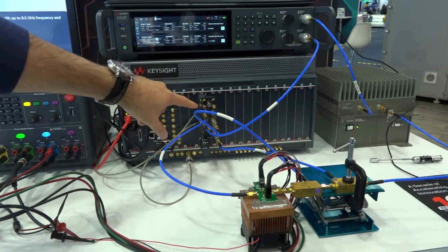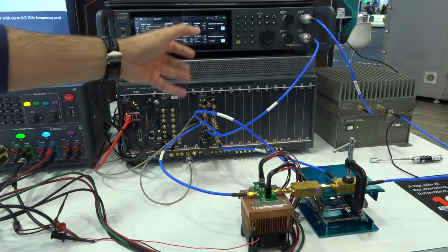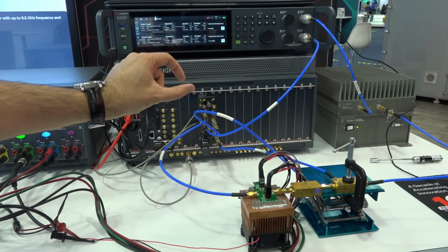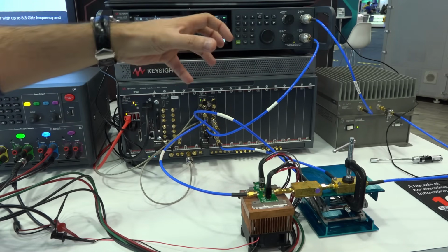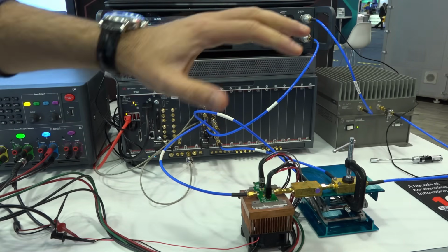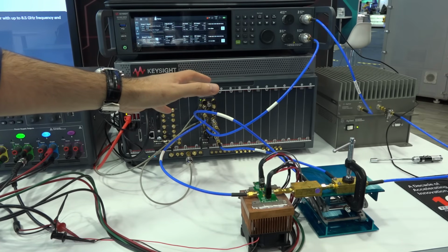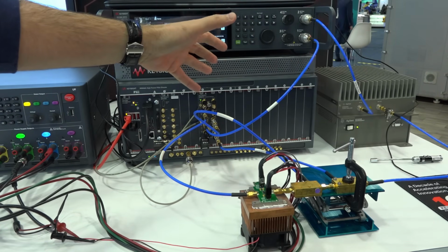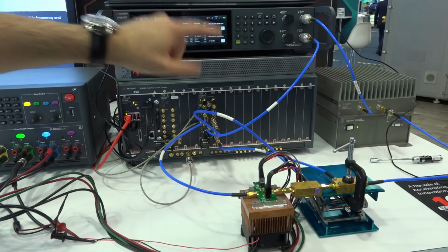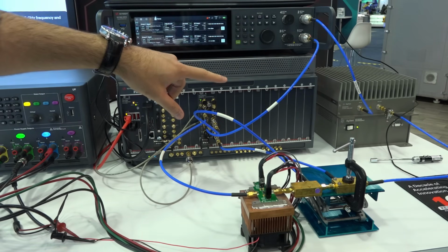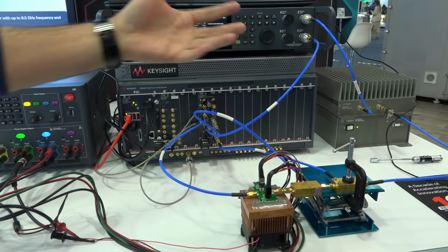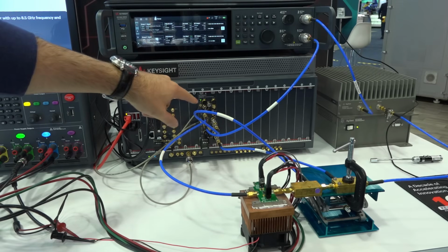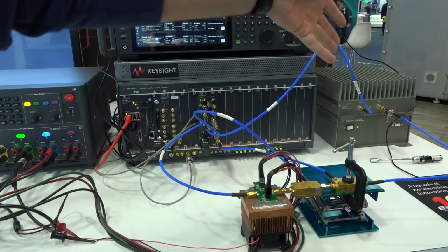Well, if you have one of these PXIe network analyzers with direct receiver access, you now can digitize this entire bandwidth in sections and then assemble that together and not only extract the EVM, but also all of the nonlinear parameters from this amplifier at the same time. And you take all those nonlinear parameters and you pass them into Keysight EDA tools. Now you have the model of the amplifier directly based on the dynamic measurements of this active load pull, put that in your simulation, and then go back and forth validating what you're looking at. So here we're combining RF synthesizers, direct access receiver network analyzers, and of course DUT and amplifiers.